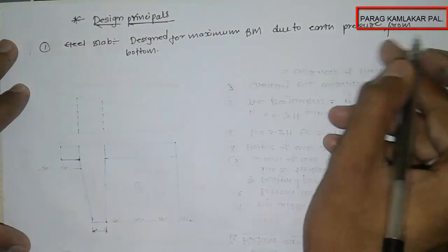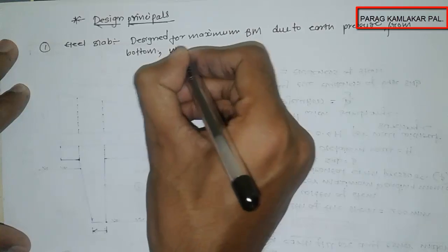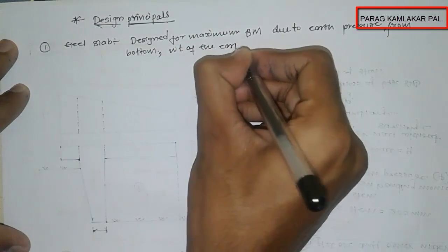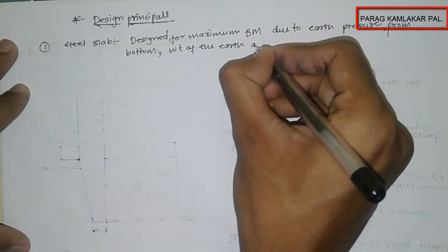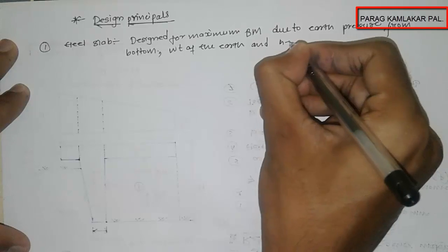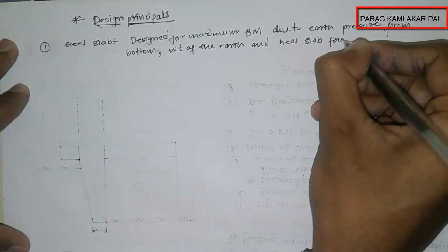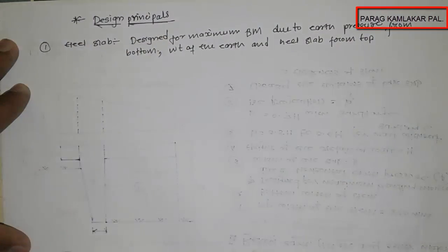Not only the pressure from the bottom, we also design it for the weight of the earth and heel slab from the top. So this is what about the heel slab.